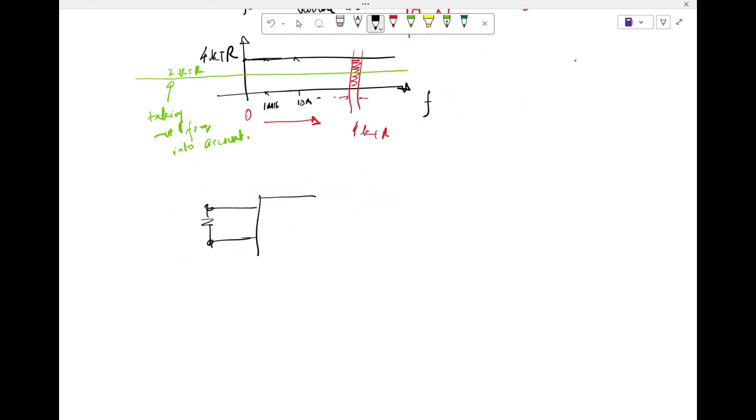And after that, I have a block which acts as an amplifier and gives a voltage gain of A. By the way, A is a voltage gain I'm talking about here. Not power gain, not current gain, it's a voltage gain. And let's assume that the input impedance is infinite. Right. Okay. And I observe the output here, V naught.